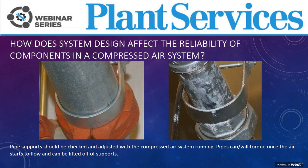One other thing that we see is, as installed, pipe hangers might be holding the pipe properly, but as soon as the system turns on and there's air going through the system, these pipes will torque. So you need to go back when the system is on and recheck all of the hangers to make sure that the hangers are actually supporting the weight of the pipe. In this case, as the pipe lifted off the hangers, all of that weight gets transferred back to the compressor itself.